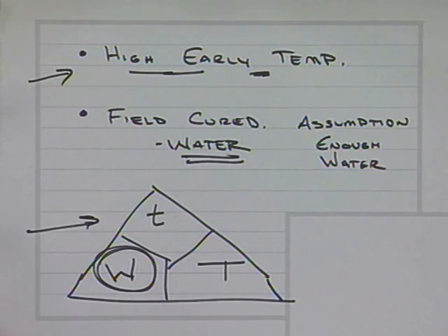Mike? Who's going to have this information, the ReadyMix guy? You'll see different people with it. Sometimes the ReadyMix guy would have it. Typically, the ReadyMix guy is not going to do this unless it's for a real big mixture, typical mixture they're using a lot of, and someone else is going to use this. If you're seeing a paving contractor where they're using their own mixture consistently, they will have this mixture. For example, in the state of Indiana, they can open to traffic based on maturity results. So I would say every contractor I've ever talked to knows their maturity relationship up until it hits 550 psi, which is the time they can open to traffic, because that's what they really want to be able to do. Yeah.